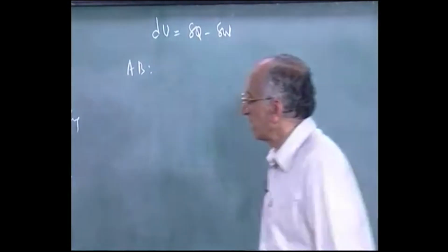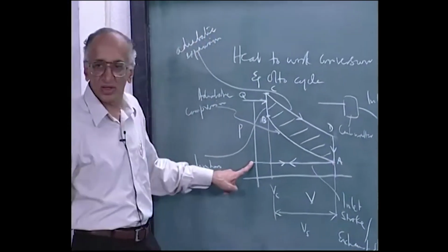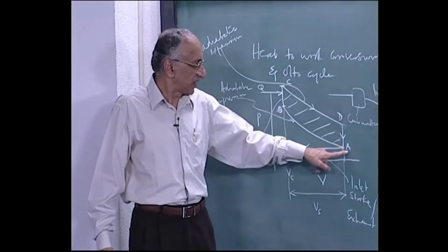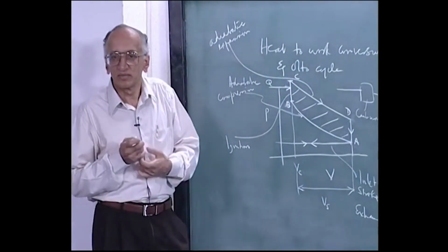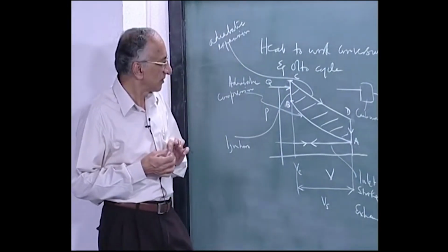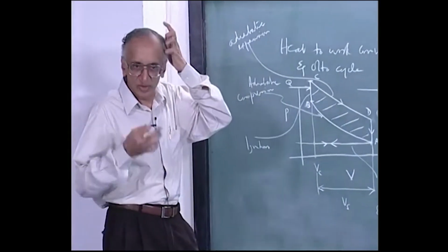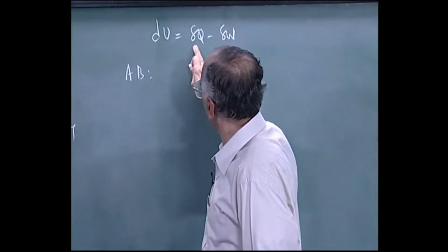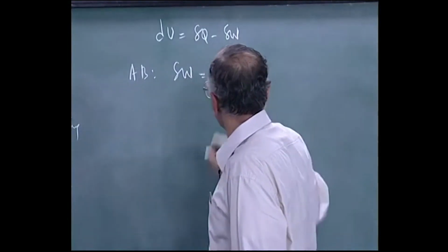So the stroke AB, I am going to ignore the inlet and the outlet strokes as cancelling one another, I do not have to consider them at all. I pretend that here I start at A, I pretend instead of fuel ignition I pretend heat addition, and I pretend here that there is heat removal, which is actually the truth, I remove it very quickly. AB is an adiabatic system, so delta Q is 0, so delta W is equal to du.